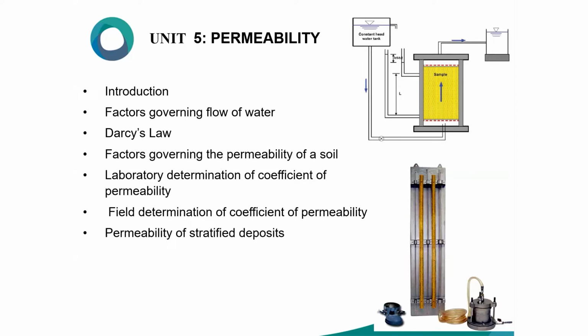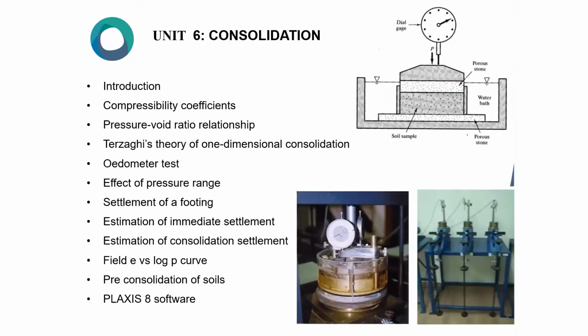It will take a long time. So to understand this behavior, we do different types of testing: the constant head and falling head tests. This is the beauty of this. Based on this experiment, you can decide whether your soil is a drainage material or not.